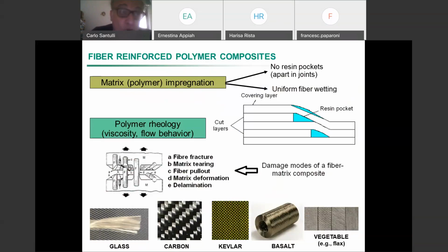I have carbon fibers or aramid fibers like Kevlar fibers. Most recently, I have introduced also some other ceramic fibers which are competitive with glass, which are basalt, and they have quite some market. Still a few percent, but they have some interesting characteristics, especially the fact that they need less treatment and less production cost than producing glass fibers.